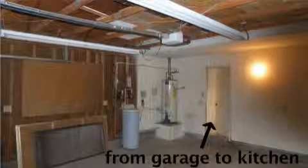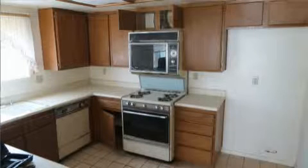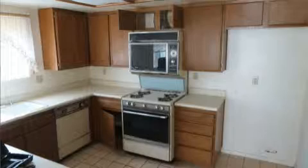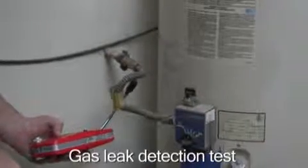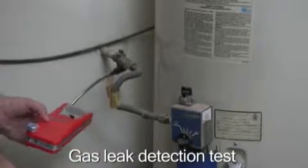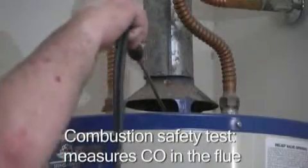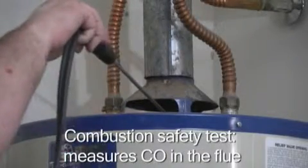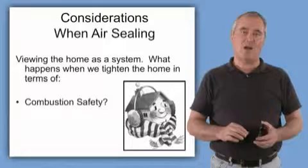So there's more of a competition for air between bathroom exhaust fans, kitchen range exhaust, and that competition may cause an atmospherically vented water heater located inside the house to backdraft, spilling its combustion byproducts inside the house. So as we air seal, before we begin and after we finish, we need to assure that we haven't negatively impacted combustion safety.